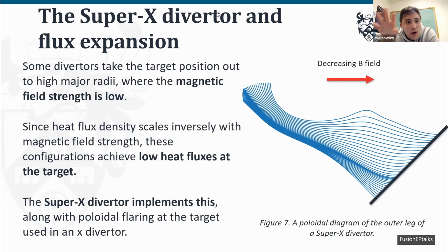You can, but regarding the poloidal field coils or any coils really, I think the main issue with proximity to the plasma, especially for future devices, is shielding and insulation and things like that. Devices like MAST Upgrade have a lot more wiggle room today. But you focus on a machine like STEP or SPARC or ITER, and there are a lot of requirements. You have field coils and target and outer vessel, and you need a lot of stuff in between. You need neutron shielding, you need pipes and insulation to take all that heat away. So that I'd say would be the issue with a poloidal field coil.